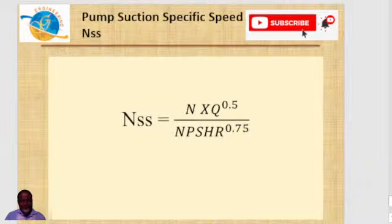Like I said, your N is the rotational speed expressed in RPM, while your Q for this case is the flow rate per impeller expressed in cubic meter per second. Your Q will be the total flow rate for single suction impeller, and it will be what?